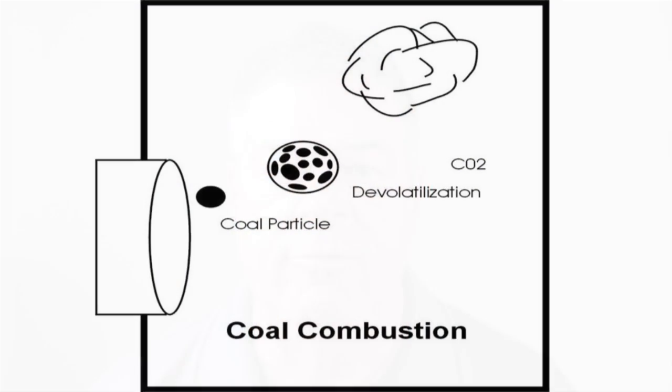What I thought I could do is just briefly give you some visual diagrams of some of the mechanisms that I see with water wall slag formation. So the first picture I'm showing you is a particle of coal that, when it comes out of the pulverizer, devolatilizes, loses its moisture, and begins to burn and eventually ends up as CO2.